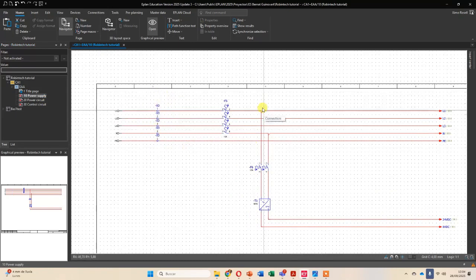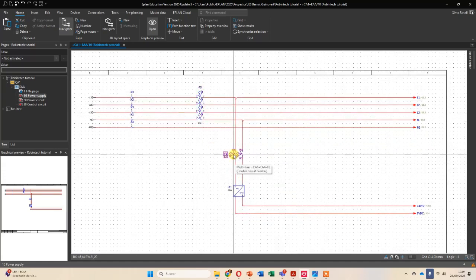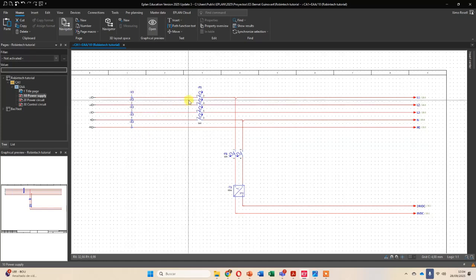Anytime we insert a macro, we have to be very careful with the data tags, device tags that we have, okay? Because in some cases they might be wrong and we will have to rename them, okay? But when the project is empty, not like this one that I've been using, there shouldn't be a problem and everything should be alright, okay?